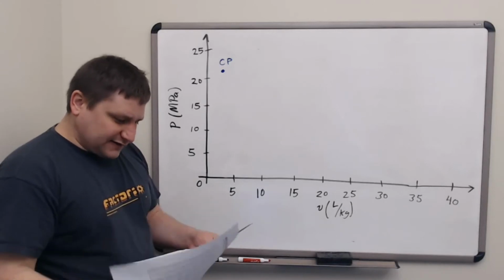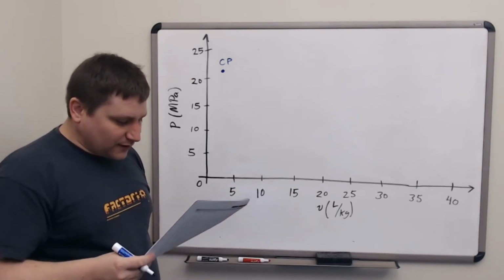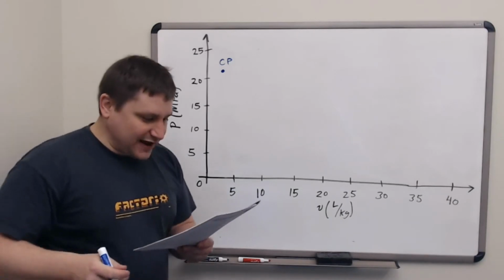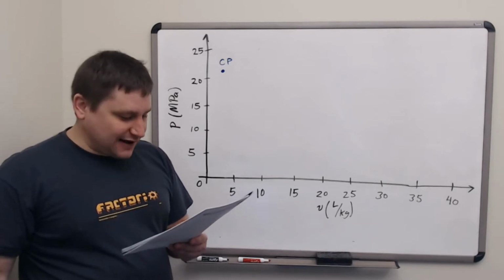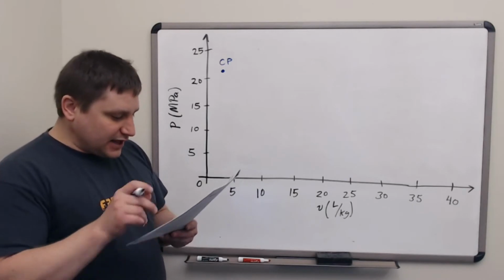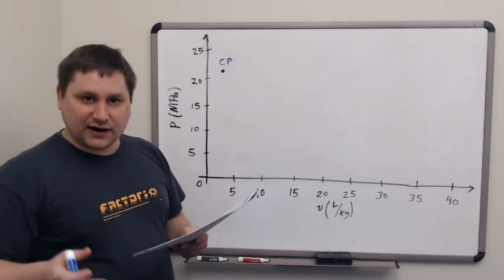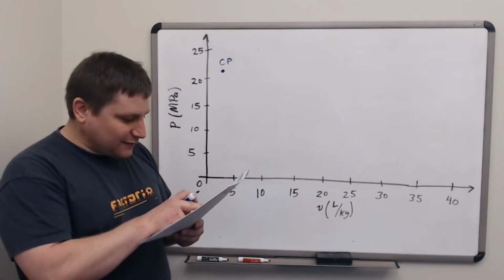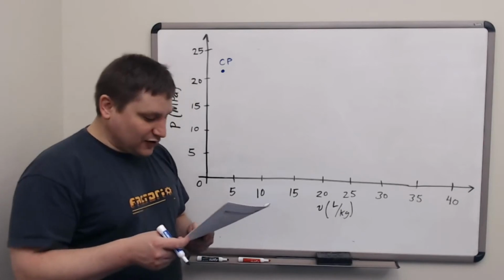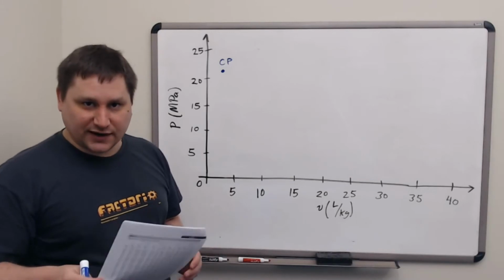Now let's get our bearings with this table some more by going back to the first page and searching for the row that is labeled 101.325 kilopascals. This is atmospheric pressure. We can see that the phase transition temperature, 99.97 degrees Celsius, is the phase transition temperature for the boiling of water. If we check the volume of the fluid, it is 1.043 liters. Water has 1 liter per kilogram. If we check the volume of the gas, 1.6734 meters cubed, we get the volume that would be present for water vapor at the boiling point for 1 kilogram.